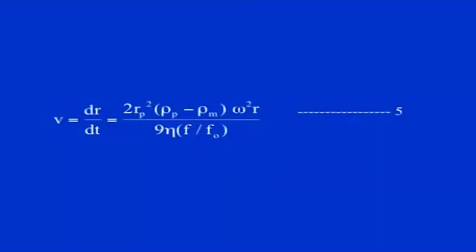Now, these include, one, it is directly proportional to the size of the particle, where I was telling you the radius r p of the particle, and since the equation involves the square of the particle radius, it is apparent that the size of the particle has the greatest influence upon sedimentation. If you recall, here it is r p square, the radius of the particle. So it has quite a lot of effect on the sedimentation: if the particle size is doubled, the sedimentation rate will be more.